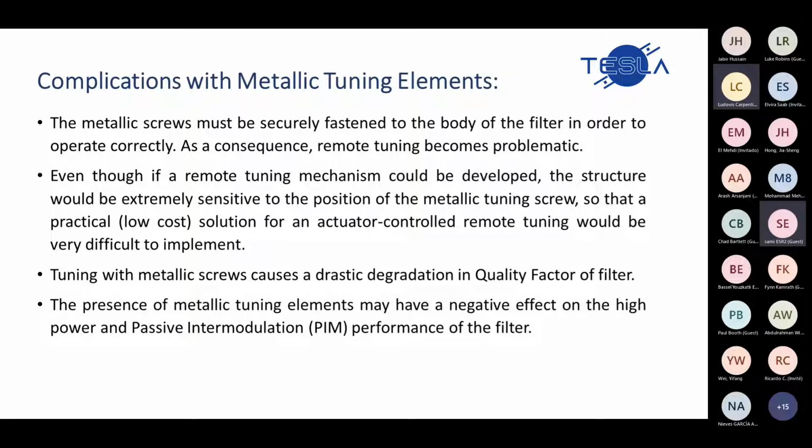And the last one is that when we use the metallic screw, it has a very negative effect on the power handling and the passive intermodulation performance of the filters. So that's why we intend to move to the use of a dielectric tuning element rather than the metallic tuning element for our filter topology.